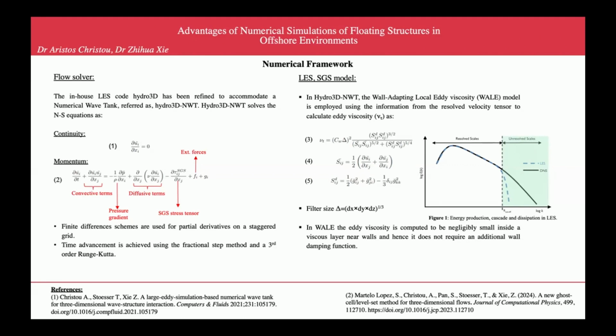Most important part of this code is the large-eddy simulation methodology. And as we can see from figure 1, we have the direct resolved velocity tensor from an area or for large flow structures which are greater than the grid size usually, and it's similar to the DNS, where flow structures smaller than the grid size and their dissipative effect is calculated or actually modeled using a subgrid scale model.